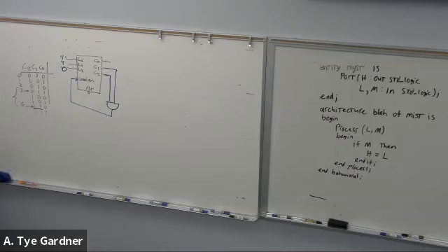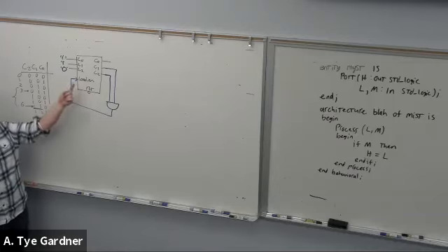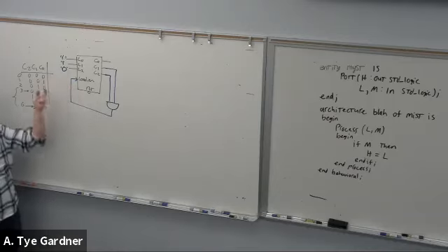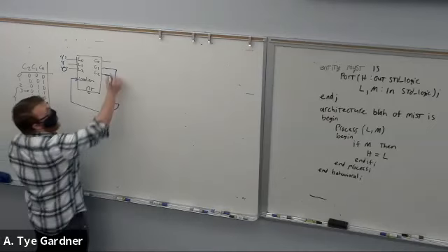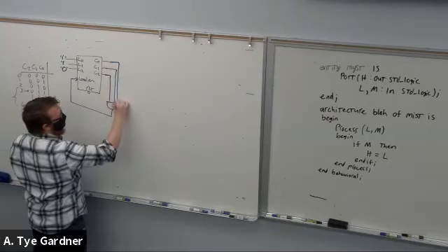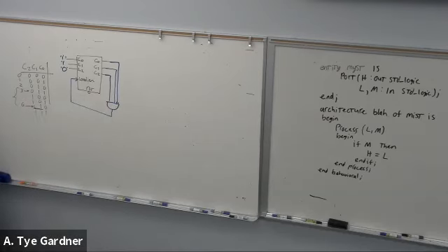If I was trying to count from 0 to something, then I could just plug into the reset or the load and have 0, 0, 0 at the beginning, right? This, if I didn't ask for the minimum circuit, is equally correct. Something like that, right? It's just that in reality, because I should never get to 7, this last digit is really like a don't care. That makes sense to everyone? Is anyone confused on this?